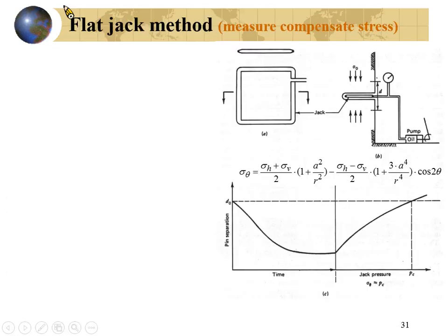Okay. Then the fracture method. As I told you, we were trying to excavate a slot and trying to measure the distance between two pins. And you will have this kind of result because the pins will close to each other, will approach each other.